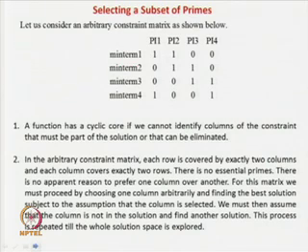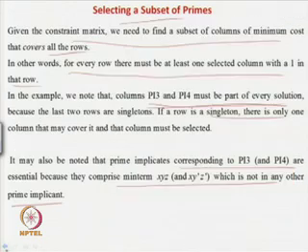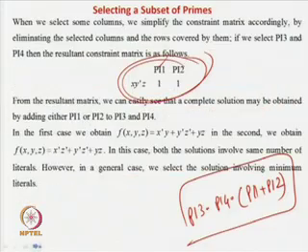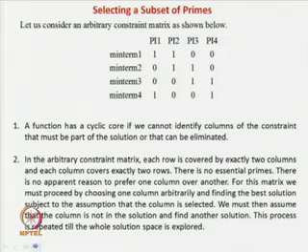Now what will we be doing? We will be looking at some preliminary or pre-processing steps before we go to the exact algorithm, which will do what I have done now. We started with this one, then removed the singleton elements, and then got to this matrix where there was a choice and we can take any one of them, and so forth. That was nothing but some steps of solving the subset of prime covering problem. In the next class we will go about a formal algorithm, or I should not say an exhaustive algorithm, formalized steps for doing it.